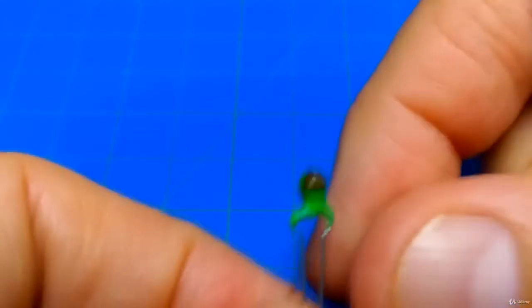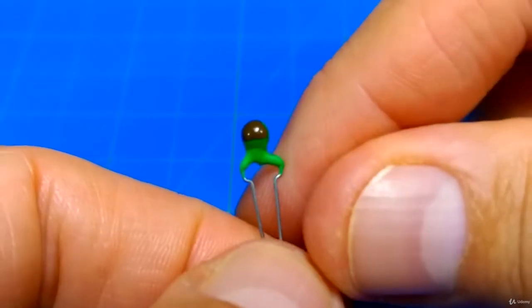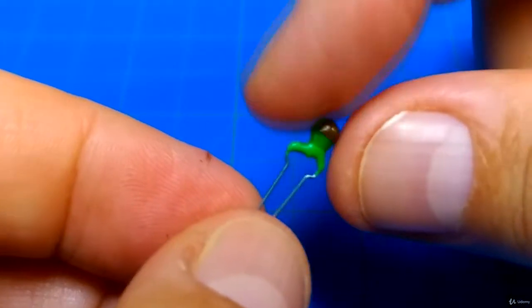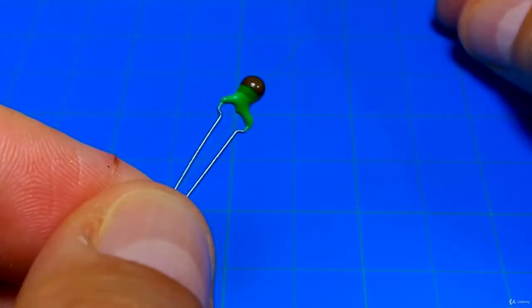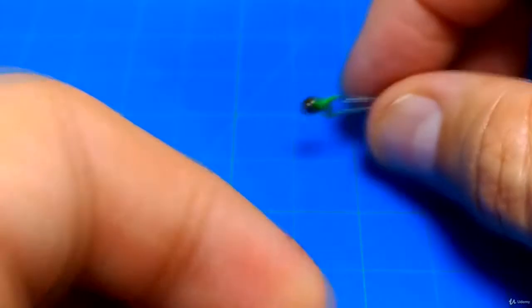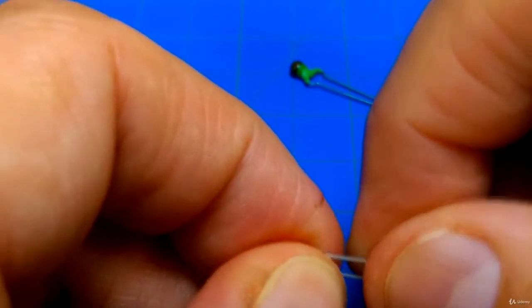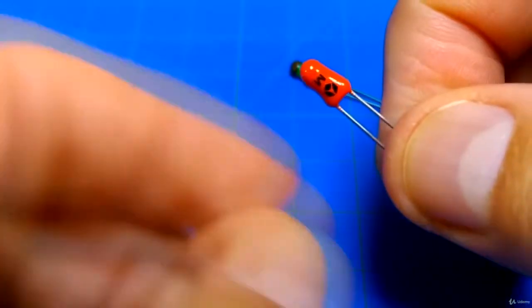Here are a couple others. All right, and there's another little tantalum capacitor, and this one I believe doesn't have anything on it. Nothing, no writing on that. So if you do not know what the value of this thing is, you are in trouble. You're going to have to use a capacitance meter, or you're going to have to put it in a circuit, and you could maybe calculate what the capacitance is if you really wanted to.